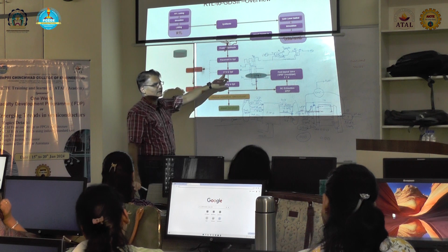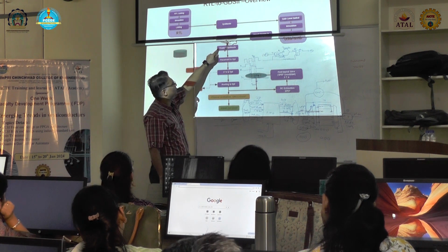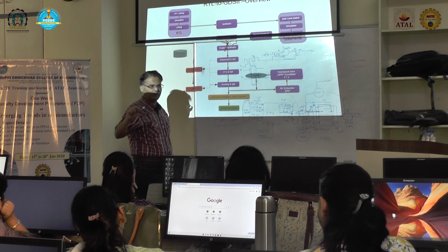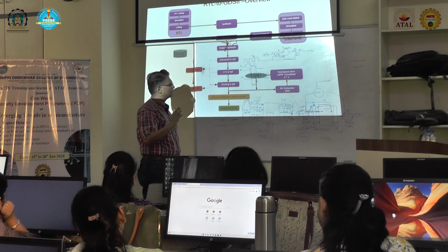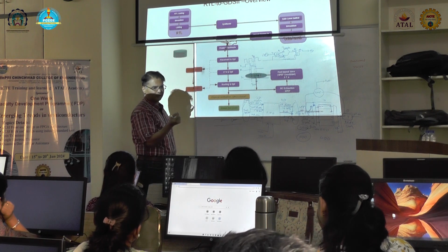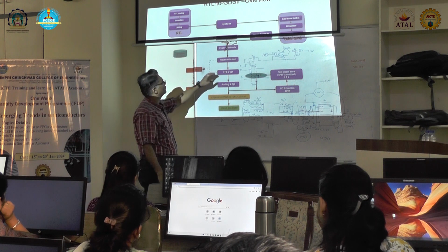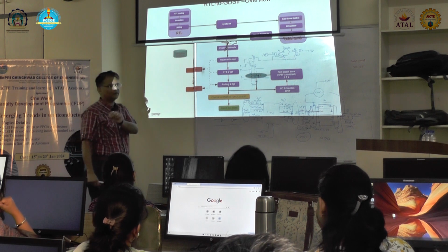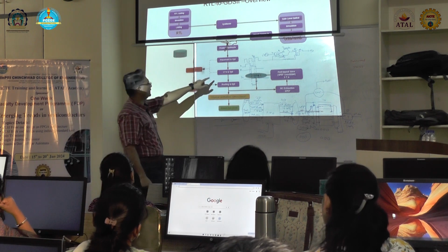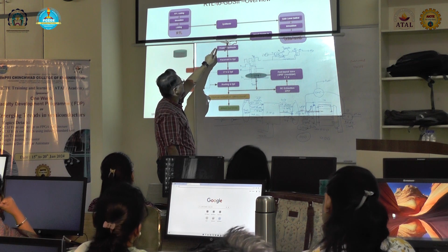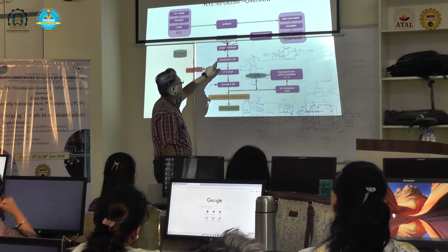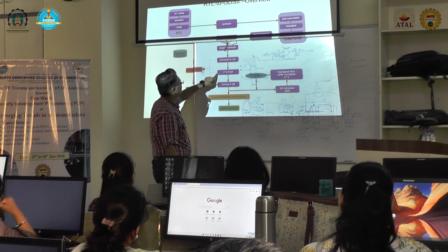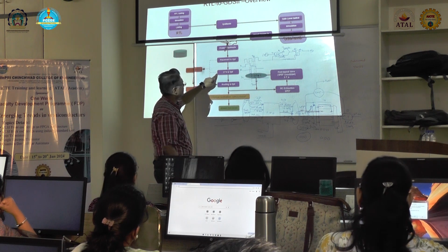And then you perform the CTS, because now you have connected the VDD and ground. Similarly, you need a clock signal for all the sequential elements like flip-flops. They require a clock signal. So you will route the clock signals to every flip-flop in the design. Okay. So until now, what have we done? We have done the power connections, we have placed the logic, and then we have done the clock connections also.